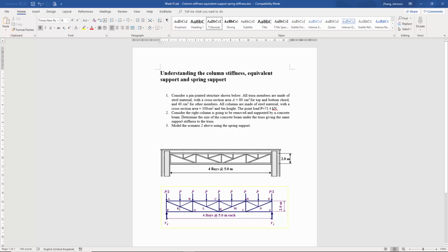There is no bar connected in the middle between joint F and joint G. The important thing is when you draw this line, it's better not to draw F to a middle point and then the middle point to G, because if this is a single bar without any line connecting from the other direction, and you put a hinge there, this is actually an unstable structure.